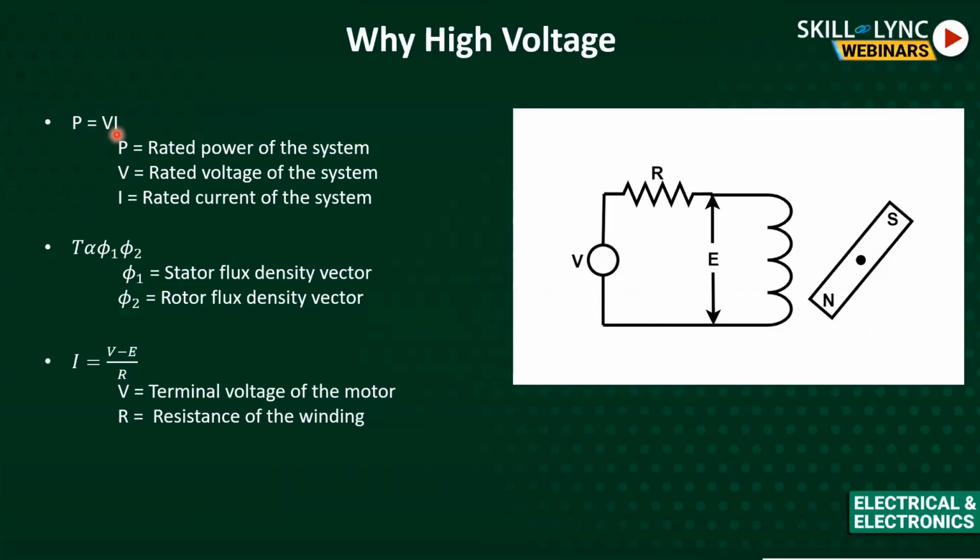In the case of larger buses, if you're talking about 12 meter or 10 meter buses, the power requirement is huge, and the motor is cheaper if the voltage is around 800 or 900 volts. This is the main reason why we are going for high voltage. You can even take the examples of Tiago EV and Mahindra e-Verito, which operate at 72 volts, but compared to higher voltage systems they are much less efficient. So the cheapest motor and the most efficient operation come at 300 to 500 volts for passenger vehicles, and around 800 volts for 10 meter and 12 meter buses.